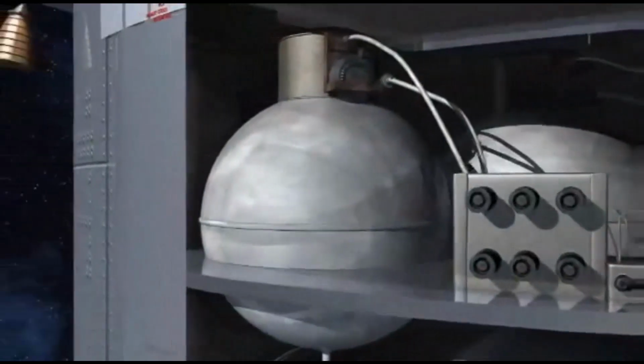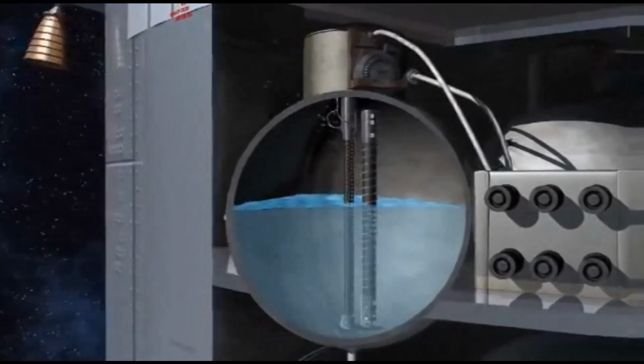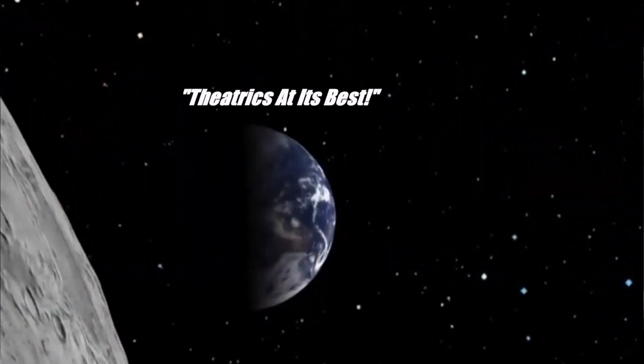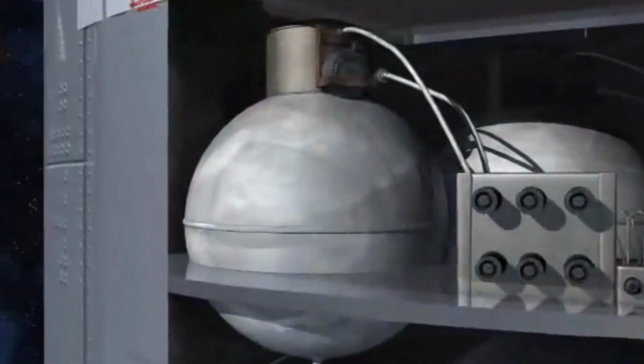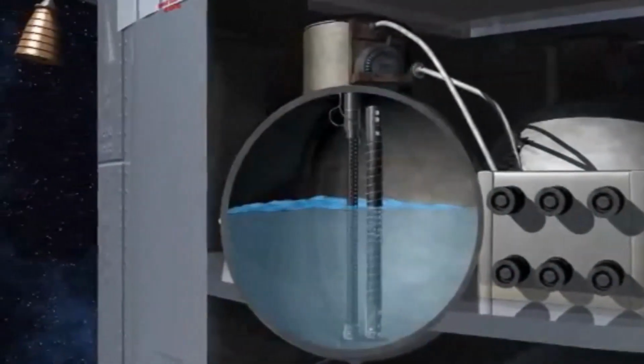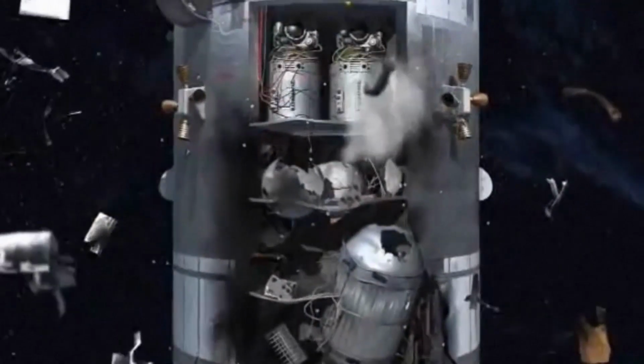And if it seems NASA was stretching its navigation technique a little, the Apollo 13 incident was another story altogether. Theatrics at its best. On April 13, 1970, Apollo 13 had an oxygen tank explosion in the service module while docked with the LM en route to the moon. Although technically it was an electrical fire that caused an overpressurization and rupture in oxygen tank number 2, which damaged oxygen tank number 1. However, the overpressurization was enough to blow the side panel off the service module, SM.